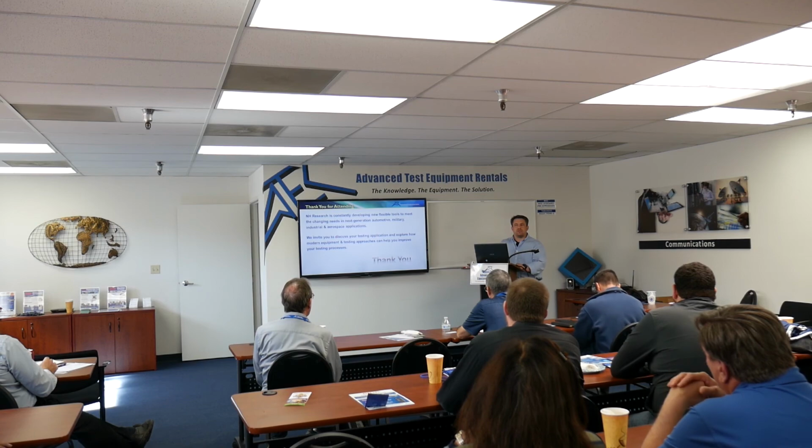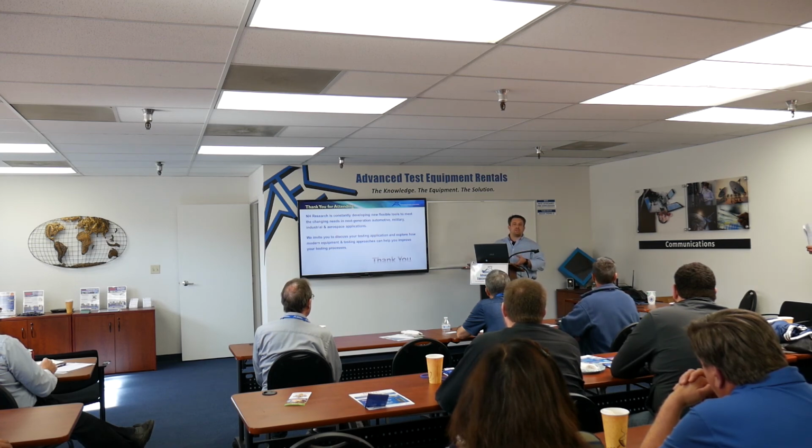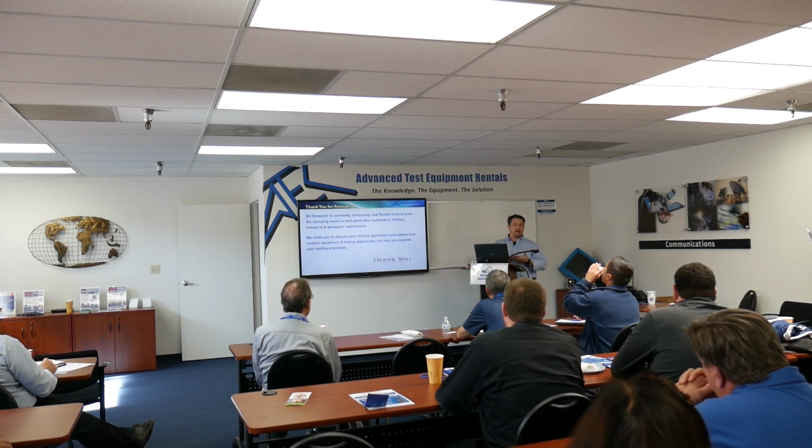But it depends on what your UUT is. Sometimes, if you're using us as a DC source, and we're powering a piece of electronics that has its own switching on the input, because we're at about 60 kilohertz, maybe you're at 60 kilohertz too, and we'll get some weird oscillation. So the ability to slow that down lets us dampen oscillations or overshoots.